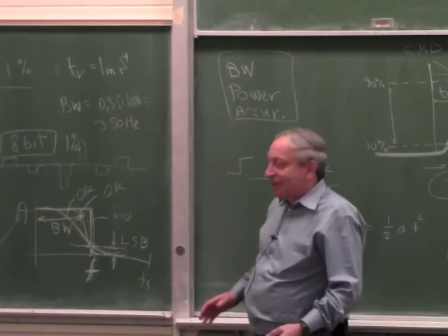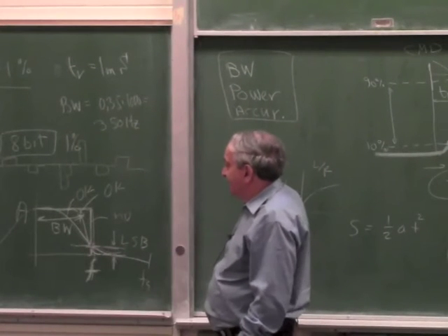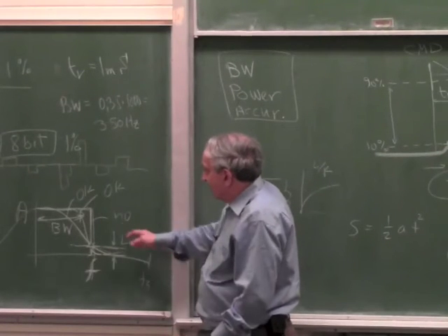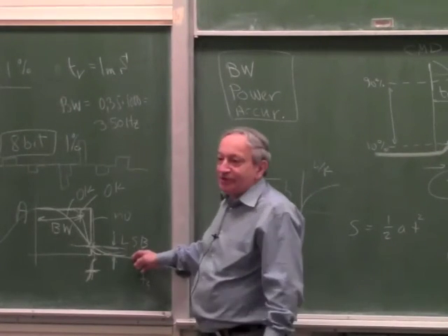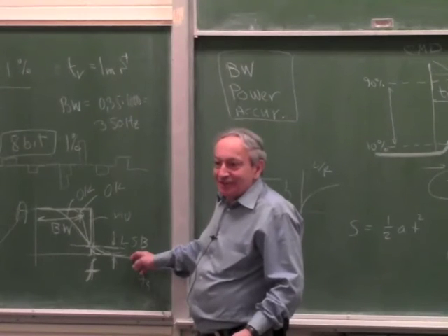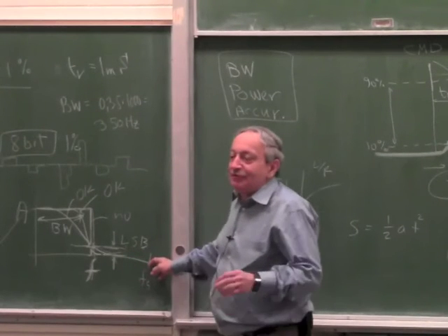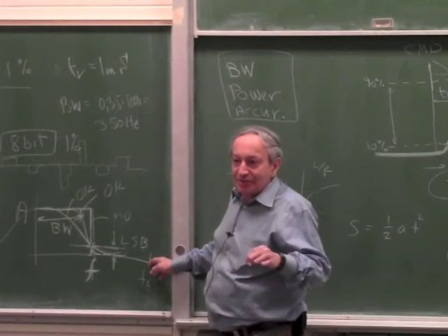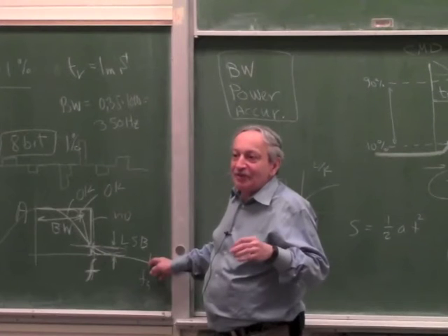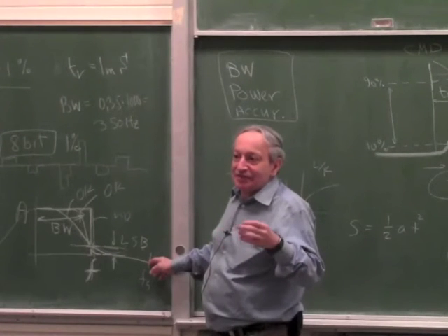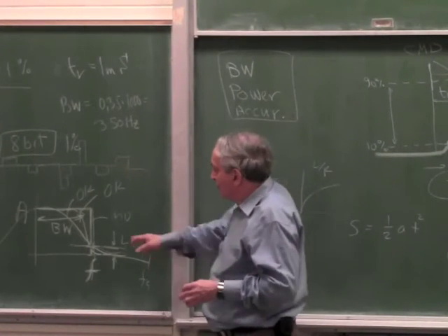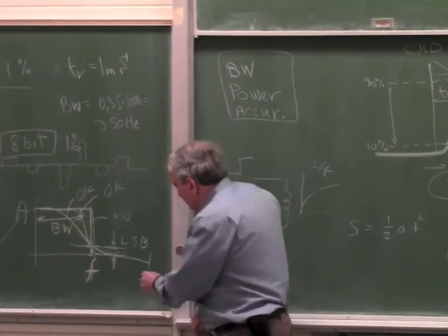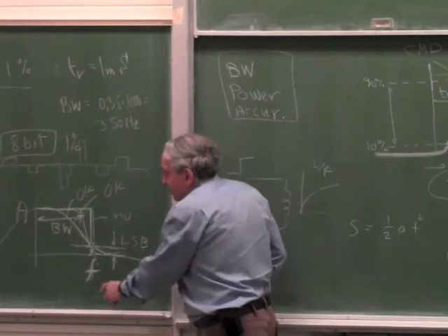Basically, the thing which determines the lower part of the graph is that you can't have like a 2/3 or 3/4 sampling frequency. You can have nothing. Because at the sampling frequency, if you have a sine wave of 1 kilohertz and you sample it at 1 kilohertz, you get just noise, just garbage. It's all aliased. So in order not to have aliasing, the signal should be less than half the sampling frequency. We went through this. So if you don't want to introduce even one least significant bit of aliasing, then this should be half the sampling frequency. This is F and this is half F sampling.